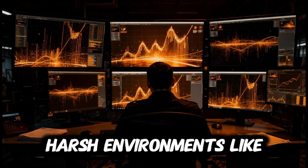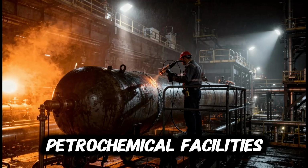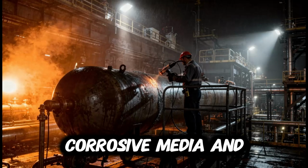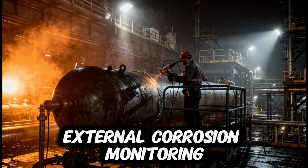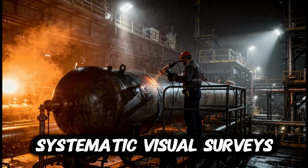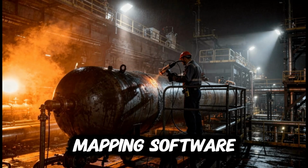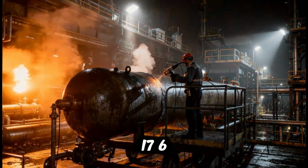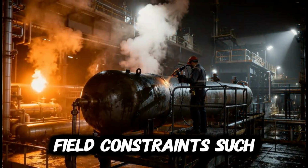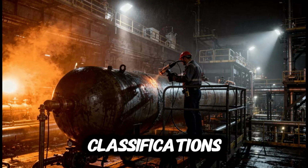And what about harsh environments, like petrochemical plants? Visual inspection in petrochemical facilities addresses components exposed to extreme temperatures, corrosive media, and cyclic loading. External corrosion monitoring on pressure vessels, piping, and storage tanks relies on systematic visual surveys documented through digital photography and corrosion mapping software. Inspectors apply ISO 17637 lighting requirements while accounting for field constraints such as confined space entry, elevated work platforms, and hazardous area classifications.